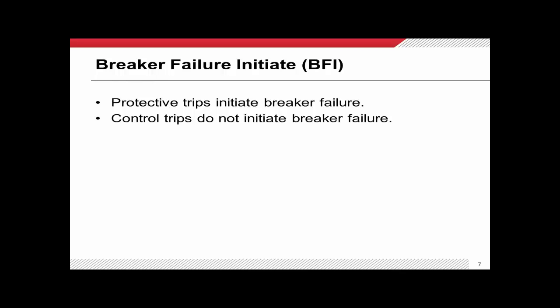Okay, breaker failure initiates. Let's spend a little bit more time talking about those. All protective trips initiate breaker failure. However, control trips do not. So you're not going to wire a contact from your control switch or from SCADA to initiate breaker failure.